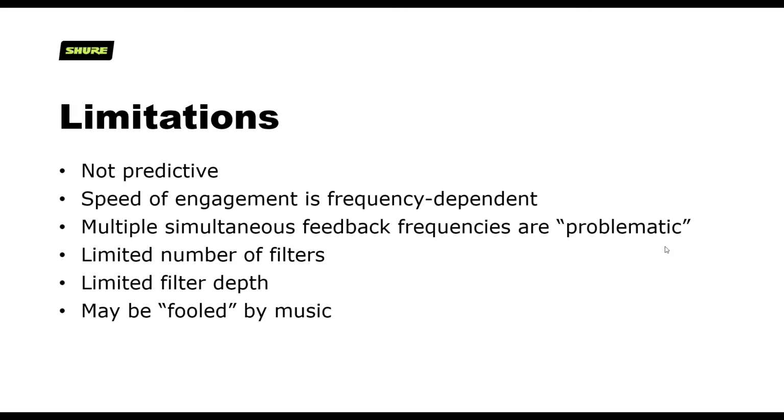There's a limited number of filters. That means it's not just going to keep throwing filters out there every time a new frequency starts feeding back. It might be 10 or 12, maybe 20 at the high end, but there is a limited number of filters. Also a limited depth. It can't keep infinitely reducing that frequency. It typically goes to a maximum of about 18 dB or so.